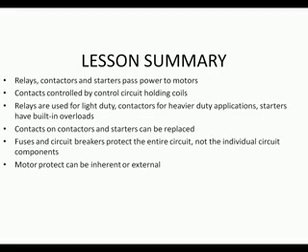So we've talked about relays, contactors, and starters. They all pass power to motors. Contacts are controlled by control circuit holding coils, or just the relay coil or contactor coil. Relays are used for light duty, contactors for heavy duty, and starters have built-in overloads. Contacts on contactors and starters can be replaced, not in relays. If a contact goes bad in a relay, replace the relay.